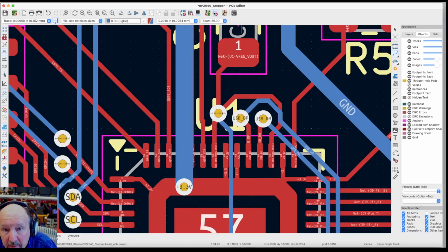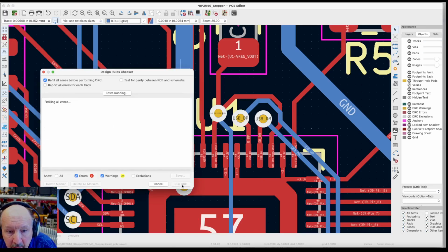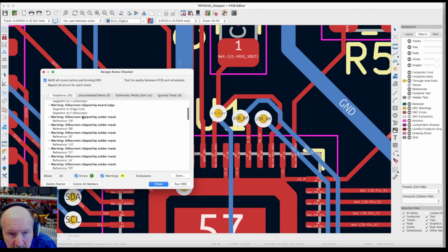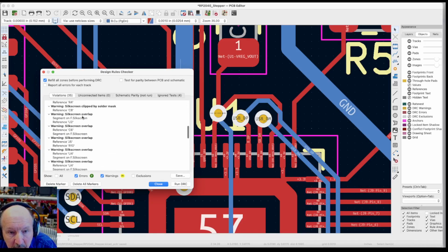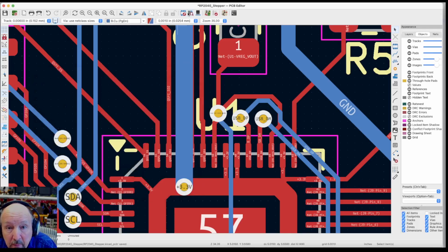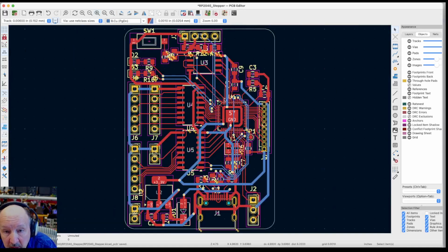0 in router. Okay, so now we can go back and run the design rule check again. The silk screen, all the silk screen errors, we haven't looked at that yet. And we'll fix that up in the next video. Silk screen overlap, and that's all. That's awesome. Okay, back out. So here's the completed layouts. My issue now is the labels are all in the bad spots, and we will move those around before we look at possibly ordering the board. Good place to stop.